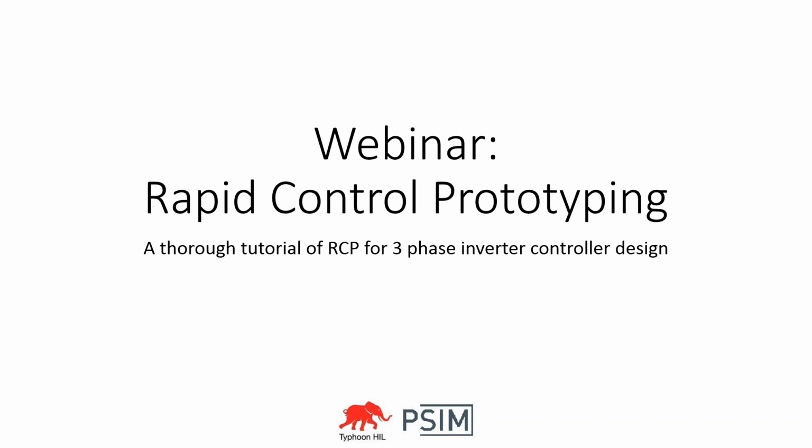There was one that was getting into motor control. How would that be mapped to the HIL? If you're using the same processor board, you would just look at the inputs and outputs of the HIL, and you would also look at the inputs and outputs of the processor and map them together, if that makes sense. It would be very similar to how it was mapped for the gate drive signals for the inverter, but you're going to have different signals.